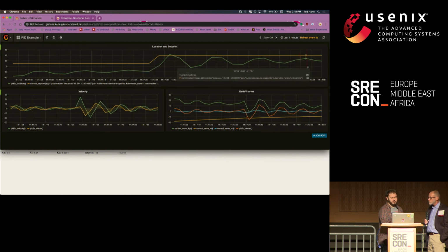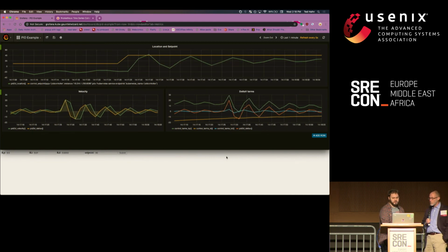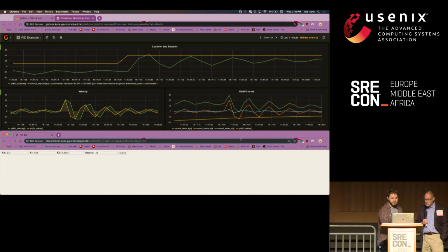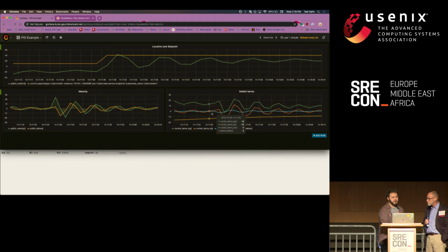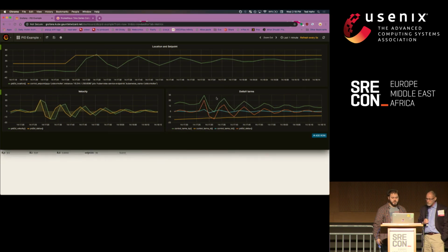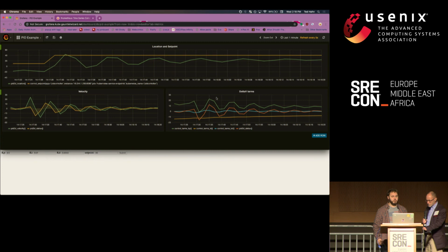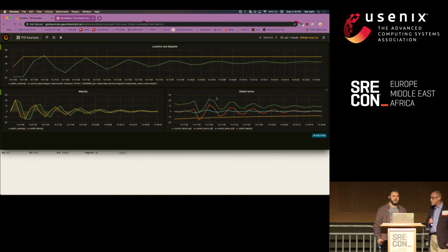And as it moves in, it is still homing in slowly. So we can continue to adjust the set point and adjust the terms that we use, the coefficients, to hone in on what our system actually wants and the desired scaling effects.